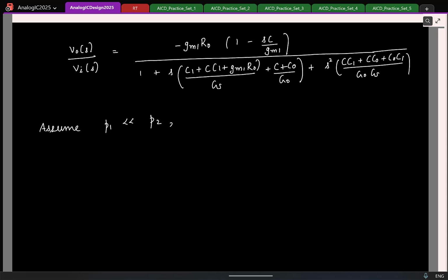I mean, we already saw in the last class, right? If I have very low frequencies, which terms here will dominate? The 1 plus s term. So you can approximate the polynomial as this. So the low frequency pole will be the ratio of these two coefficients. At high frequencies, these two terms will dominate. Take the ratios of these two. That will give the high frequency pole.